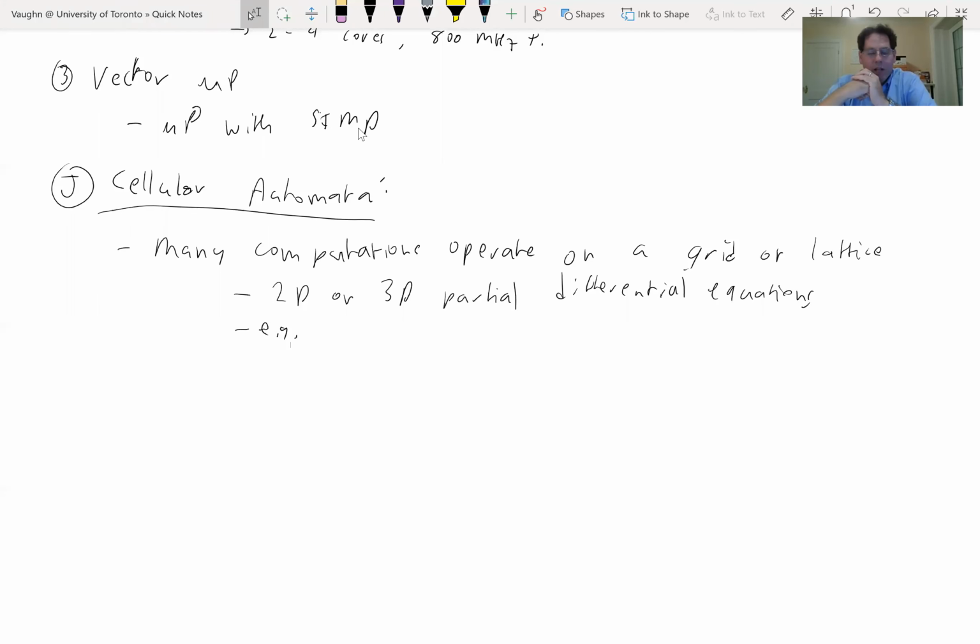And the way I'm going to do that is to apply operators at those points to calculate what my voltage is, for example, from nearby voltages. So an example of this is finite difference time domain. That's one style of physics solver, which basically takes differential equations and turns them back into difference equations.